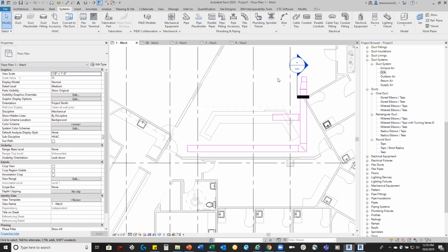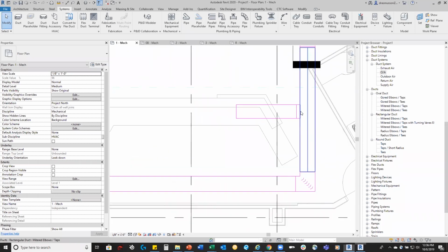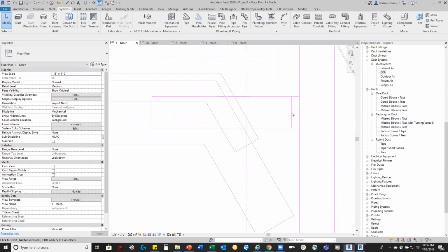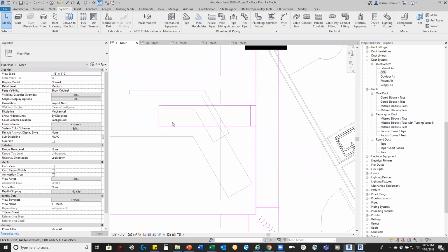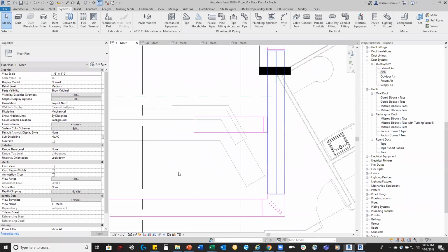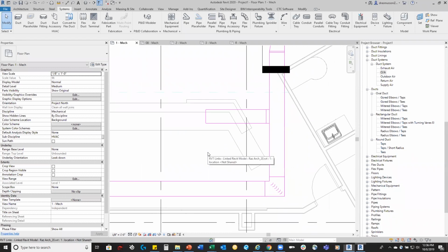Another thing that you can do are, in essence, what we commonly refer to as hockey puck style connectors. Little connectors that are no bigger than a takeoff or something like that, that are in essence a duct fitting that has one system on one side and another system on the other. You run into this commonly in building types that have, say for example, a high-rise building that may have nothing but a row of louvers above the third floor, where those louvers could be anything from connection for outdoor air intake, for an exhaust, for a grease vent, for kitchen, right? Those need to be defined where those connection points are taking effect. And since they need to be defined there, that family really starts helping you define what those connections are.